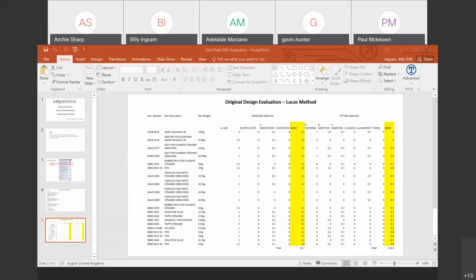What we were explained was that the design of the seat is based on a worst case scenario where the actuator itself acts as a pendulum, and the design and makeup of the seat and fish plate are all calculated for the worst case scenario. So potentially by moving the valves, you might be able to improve the design of that.